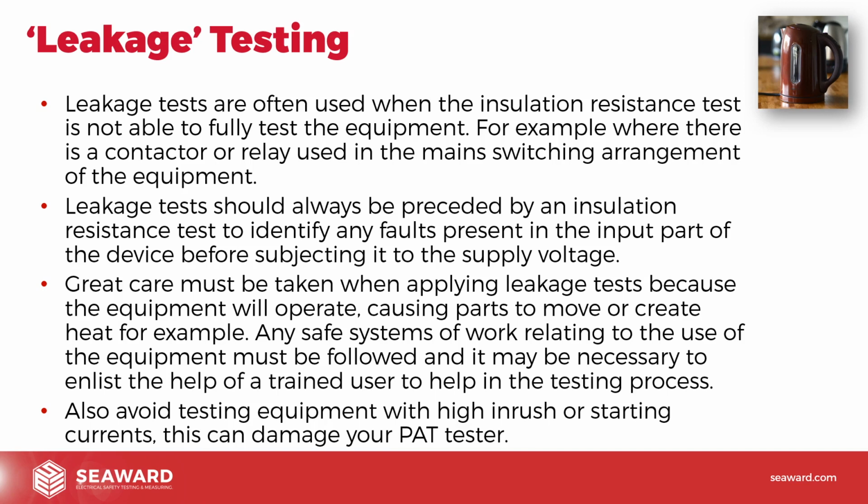Other equipment that falls into this category: we get things with stop-start buttons. So maybe in a workshop you might have something like a sander or a grinder or a saw where you've got a stop-start button. That may have a contactor built into it, like a relay built into it. So again, it's only going to turn that piece of equipment on when you've got mains power applied to it. Even later in this session, we're going to talk about things like RCDs. A lot of RCDs won't switch on unless there's mains power applied to them. So we might want to do a leakage test for equipment that's actually got RCDs protecting it, because again, we need that mains to be able to turn the thing on.